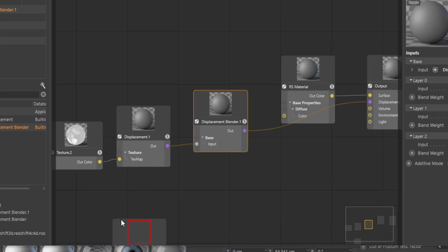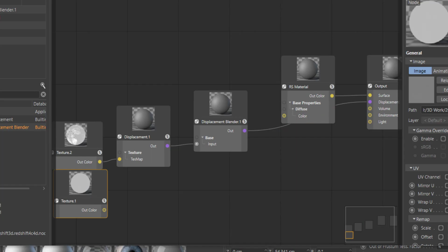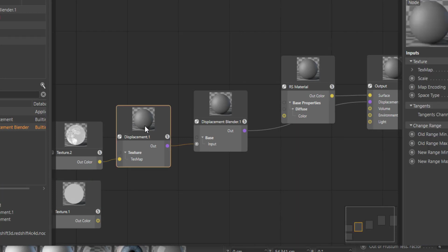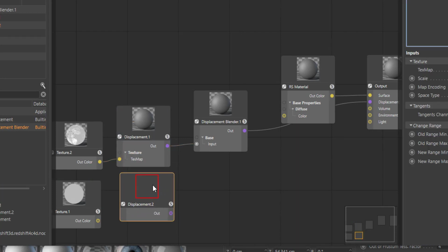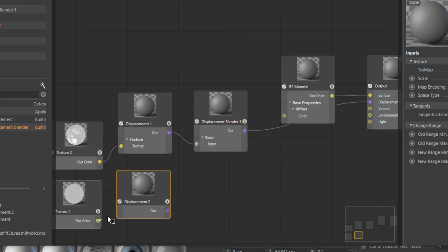So this map is going to look a bit different from the original map. You see there, there's hardly anything there at all. This is because there's not much depth, but there's more detail there than anything else. And then what we're going to do is plug this into layer 1. And wrong one. Just copy this. I'll just hold down the control key, because we still need another displacement node in there. This is so we've got independent control.